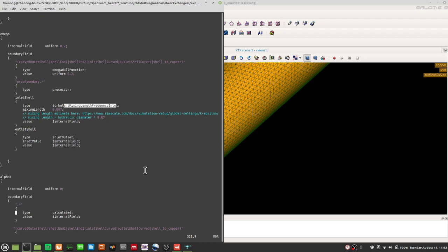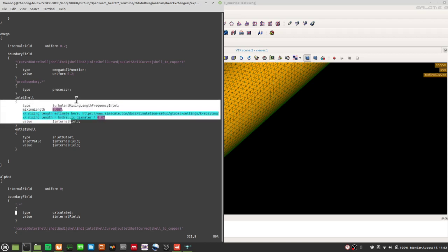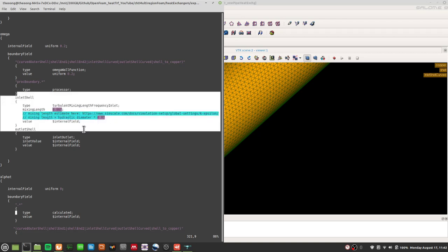Again, please go and watch my intermediate video series. I explain all of this. You just need to specify a mixing length, that's all over here. For the mixing length estimate, you can go to this website over here by SimScale, and the formula provided is hydraulic diameter times 0.07. So this is the inlet shell boundary condition I use here. I'm not going to elaborate too much on this.